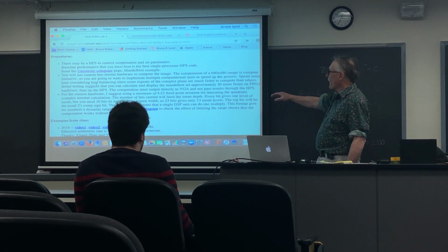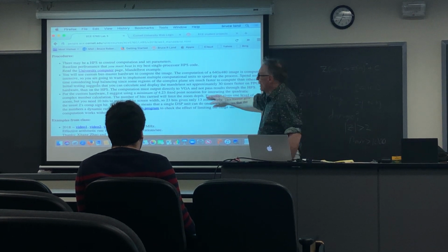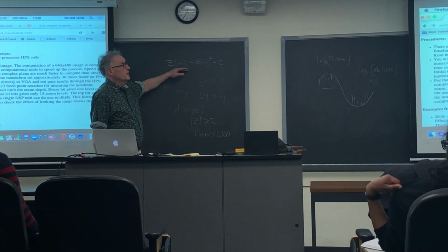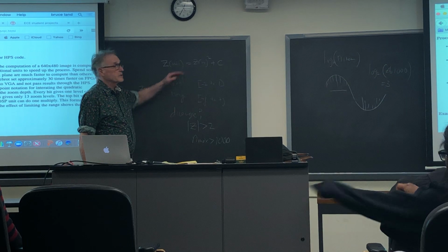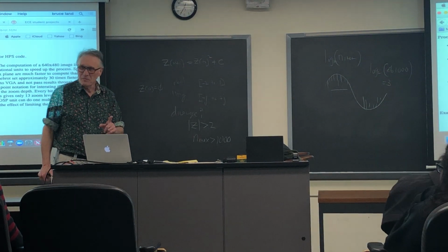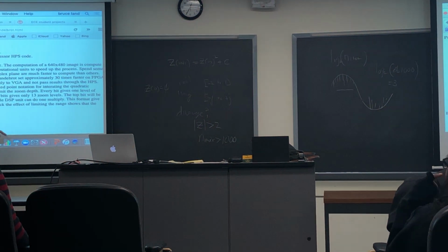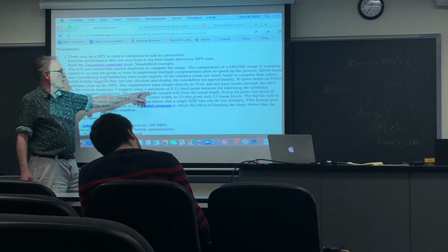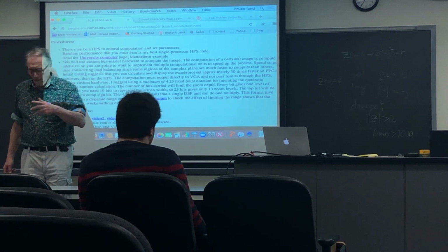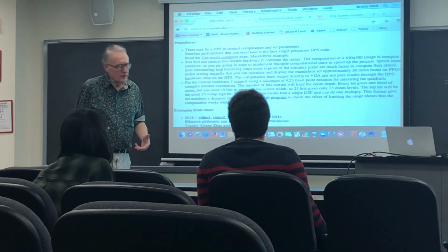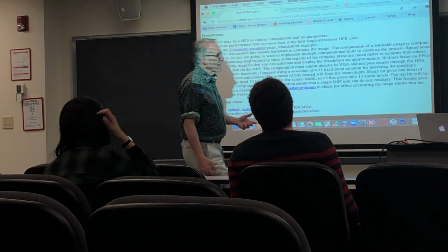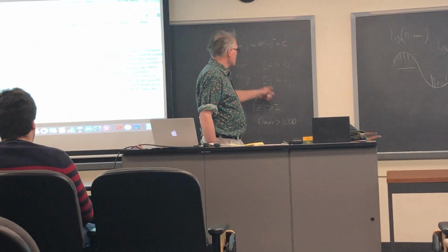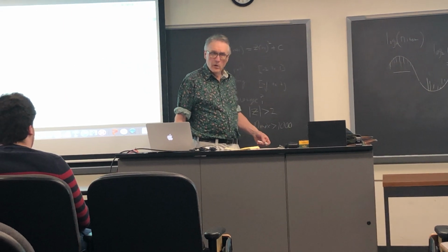And now you're going to have to write an iterative pipeline to calculate this. It's got to be a complex arithmetic type pipeline. I suggest using 4.23 fixed point, and the reason for 4.23 is you have to have a dynamic range which comfortably includes the square of 2.